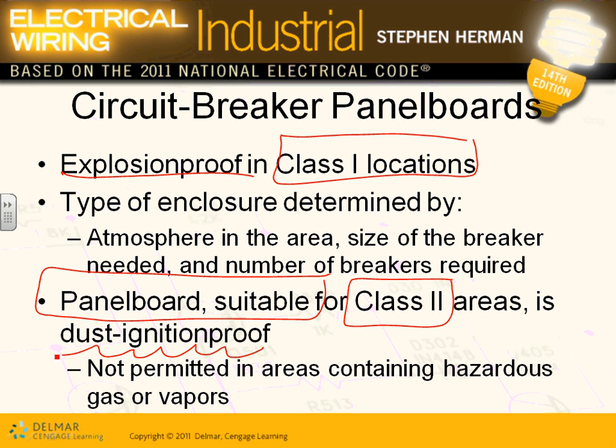Now that goes without discussion. If I have dust ignition proof equipment, can I put it in an explosion proof location? No. Explosion proof equipment though, you can for the most part put in a dust location, if they're rated for that particular dust. Again, the manufacturers got smarter than us. They rate them for both locations, especially Class 1 and Class 2 locations. Almost always the equipment can be used in either a Class 1 or Class 2 location.